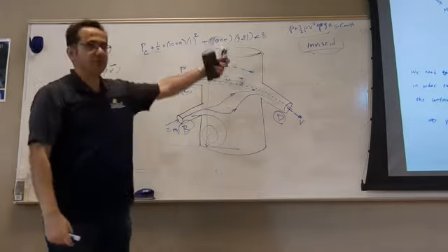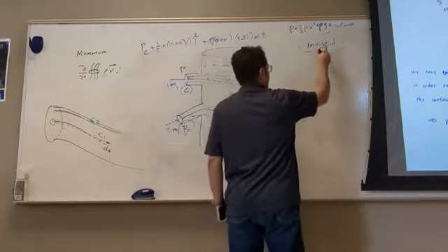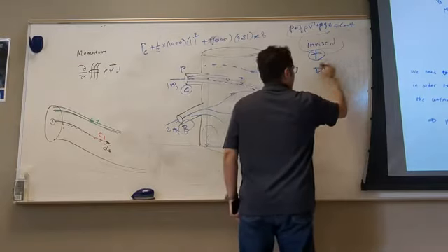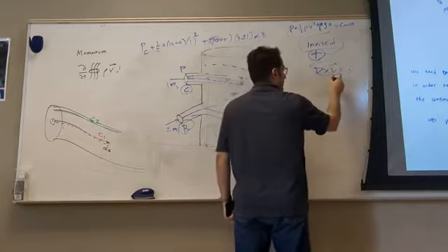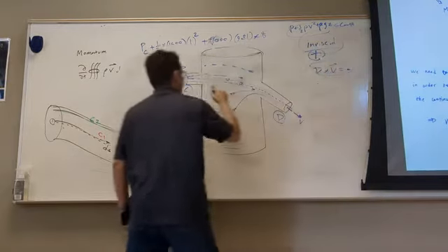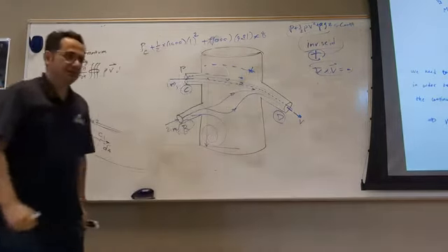What additional assumption should I make? Irrotational. Not rotation. So inviscid plus irrotational. We'll see that in the energy equation. It comes from the energy equation. If I make this assumption now, can I write Bernoulli between this and this point? Yes or no? Yes.